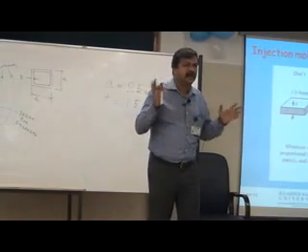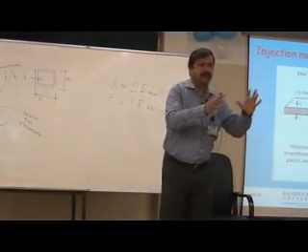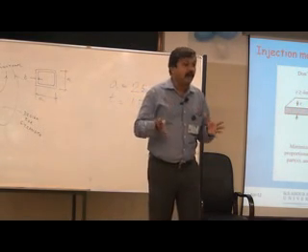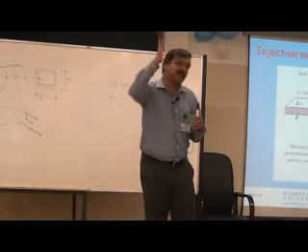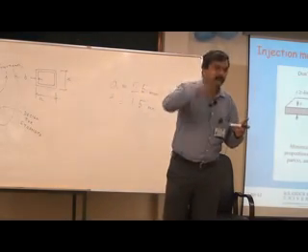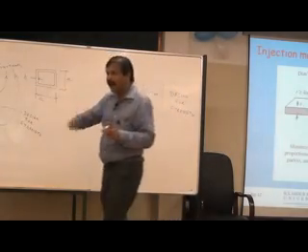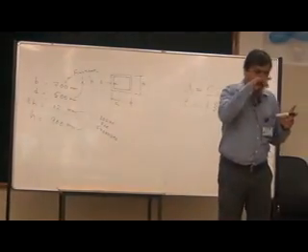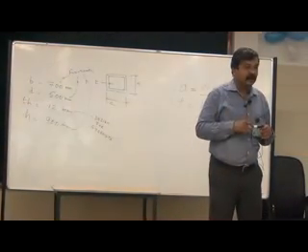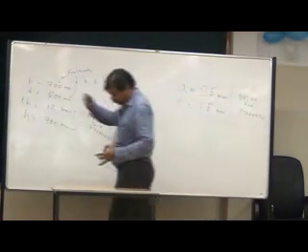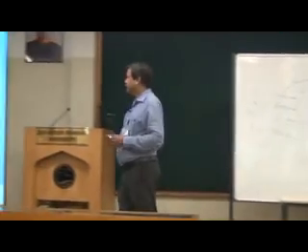So metal casting is one major category. As a mechanical engineer, you should never forget: melting and pouring is called casting or molding. Then the next category is metal forming, in which either you heat it and then deform it, or without even heating you can deform it. You change the shape by repeatedly applying huge amount of force. That is metal forming. The third category is metal cutting. So these three important categories, we will see how that is taken into consideration.